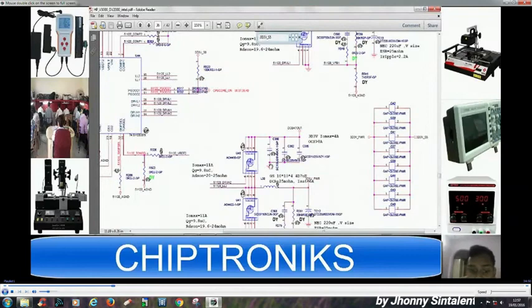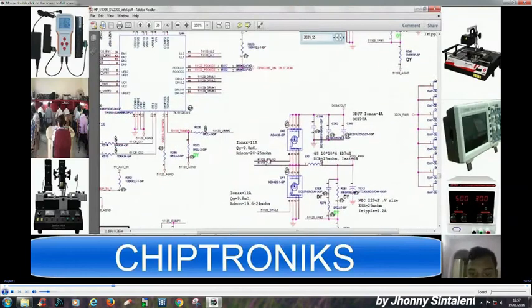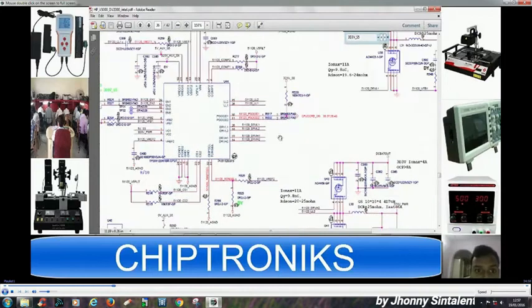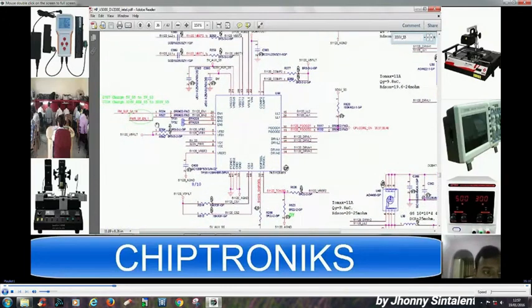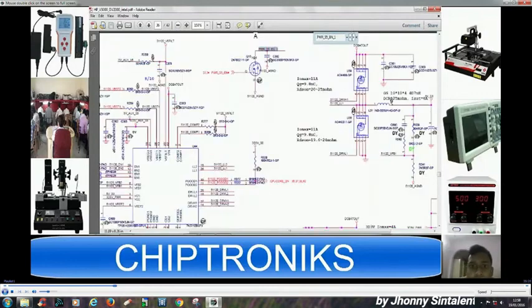Now we'll check. So to generate this drive high 2 and drive low 2, this signal is coming from this 3 volt 5 volt regulator IC, and to generate drive high 2, this EN2, enable 2, must be there. Now this enable 2 is connected from this signal. Now we can check from where this signal is coming. We'll just copy it out and we can paste. Now you can see this signal is coming from this MOSFET, right? This signal is coming from this MOSFET.